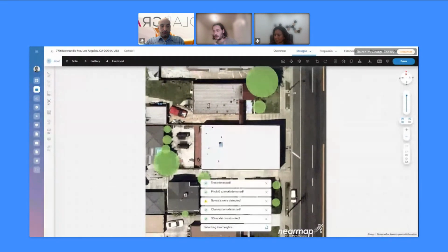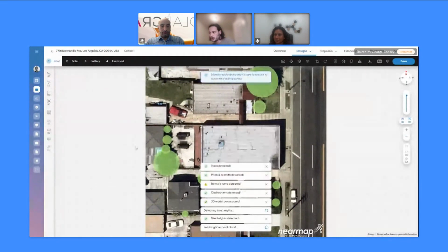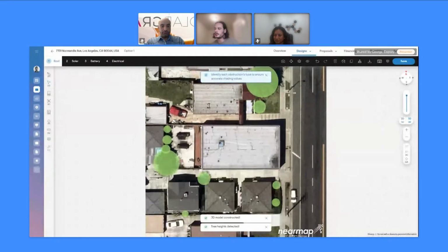It should find the pitch as flat. There isn't really an azimuth. This roof doesn't particularly face in any one direction, but the tool expects one, so it will usually identify an edge that's more or less south-facing, something that we can align our panels to.